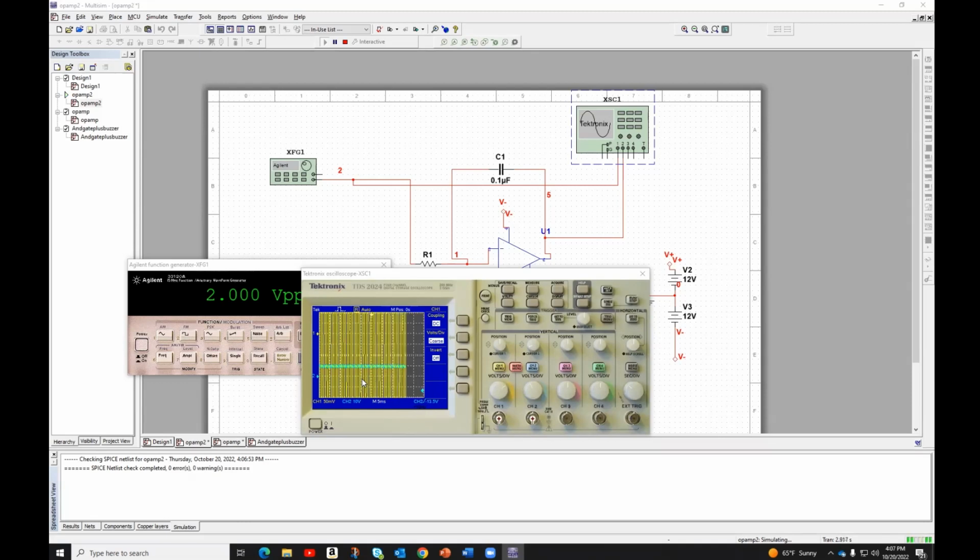One of the things you can do sometimes is use this auto set button here, it'll try to set things up for you so you can at least find the signals that you can see here. So from here, I can then select the volts and the timing to look at a little more detail, and that's what I'm doing right here. Okay, and I'm going to select the timing. Then you can see now they're both signals. If I want to move it up and down, I can do this, see the position, and I'll do the same thing with this one.